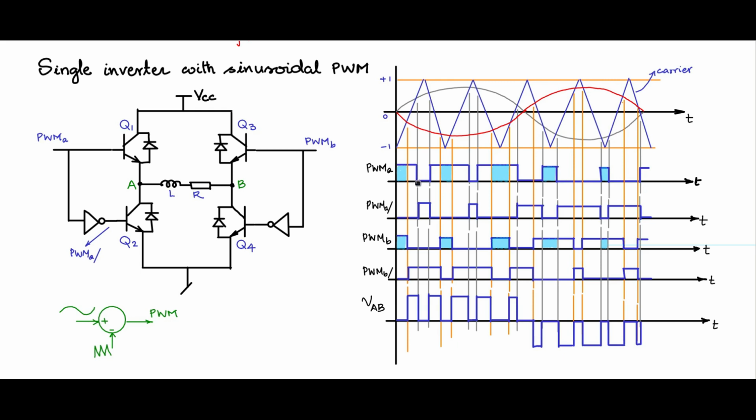They definitely are inverted, 180 degrees out of phase. However, the problem occurs at the transition. Look at this transition, which is indicated as an instantaneous transition, and at the instant when Q1 is going off, Q2 is going on at the same instant. However, in practice, in reality, things don't happen that way.